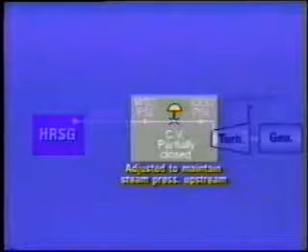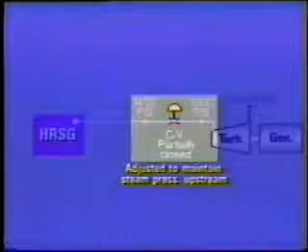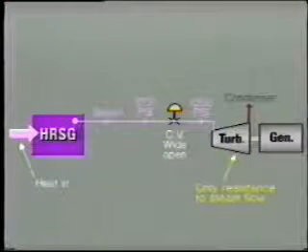The main steam pressure is really determined by the resistance to flow downstream. For example, the turbine throttle valve may be adjusted to, say, reduce steam flow into the turbine and so maintain steam pressure upstream of the valve. In contrast to this, most combined cycle units are operated with the throttle valve wide open, so that the only resistance to flow is presented by the turbine blading.